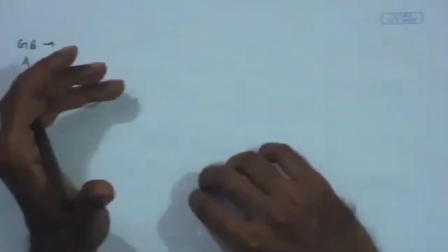Welcome back. Let us resume our discussion on the comparator design that we are looking at. Remember, starting from the ADC specifications, we arrived at some of the important specifications of the comparator. Before that, we discussed some other constituents of the single slope ADC, namely the sampling unit, where we discussed the transistor level details, what are the non-idealities that are going to come when we look at the transistor level implementation of a simple transmission gate based sampling switch.